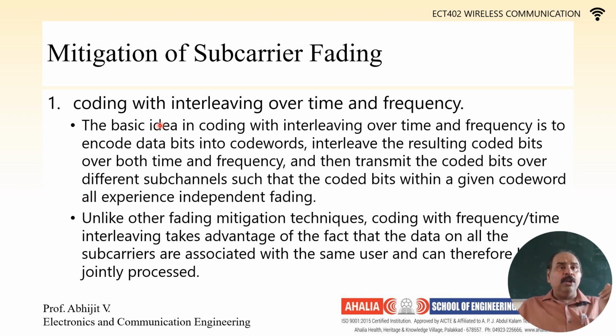So here we are going to encode the data, that is, coding with interleaving over time and frequency. The title gives you a good hint about how we are going to proceed. We are going to encode the data bits into code words and then interleave the resultant code word over time and frequency and then transmit over the different subchannels.